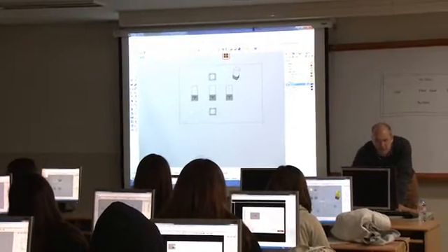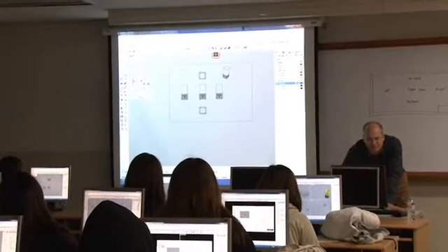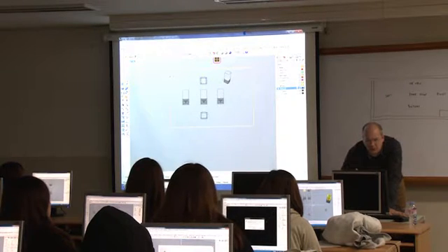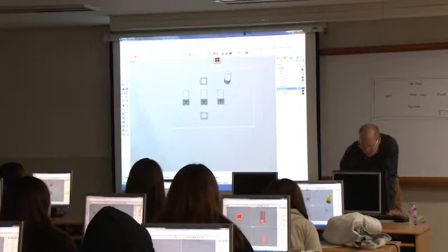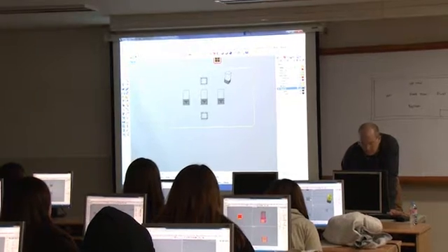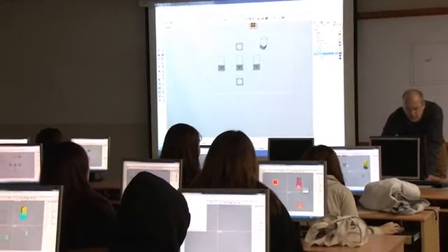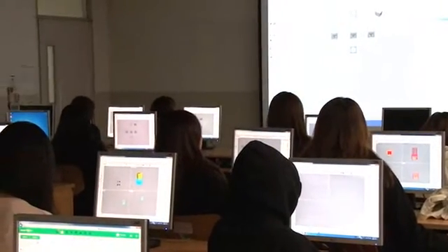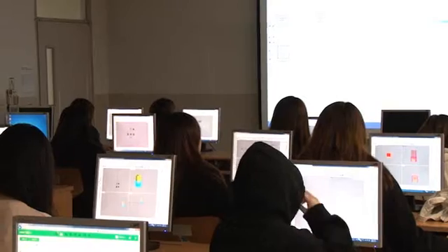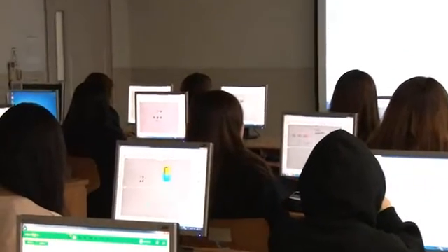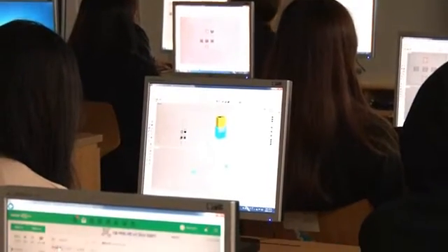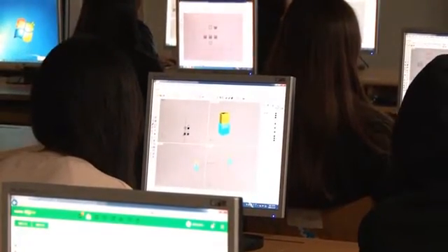I can offset my border. Offset curve. And let's go 5 millimeters or 10. Let's just do 10. To the inside. Okay, there's my double border. Oh, we're still on the wrong layer here. Let's switch layers. Select sublayer. Okay, now let's create our title block.